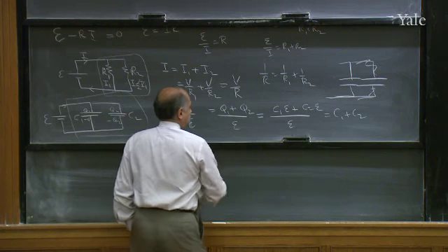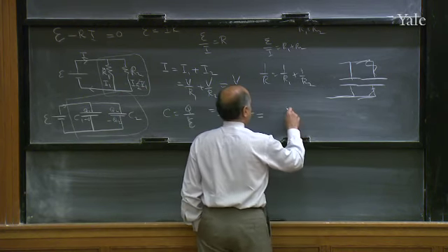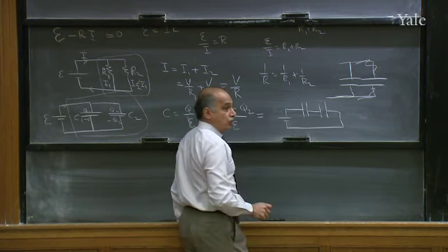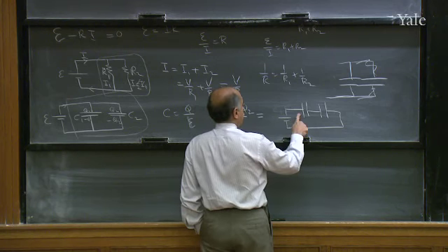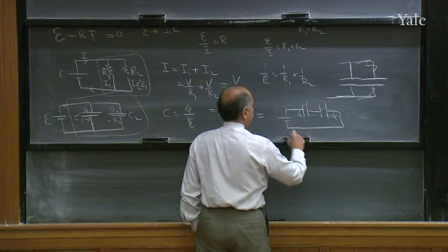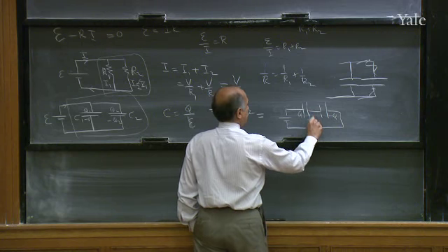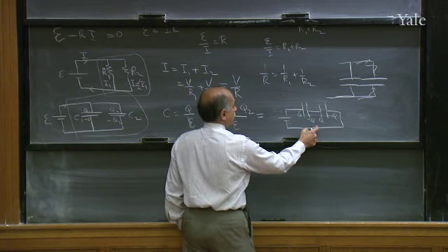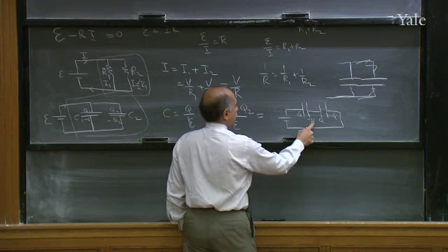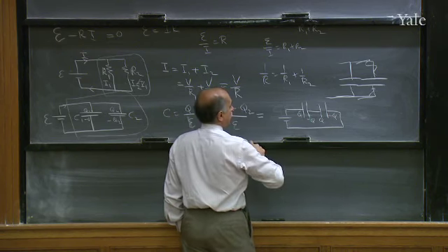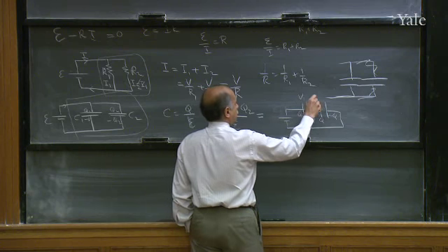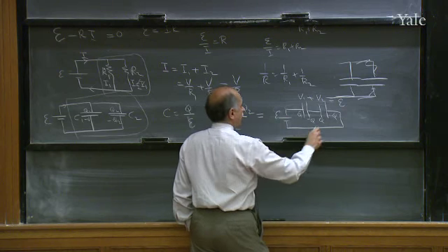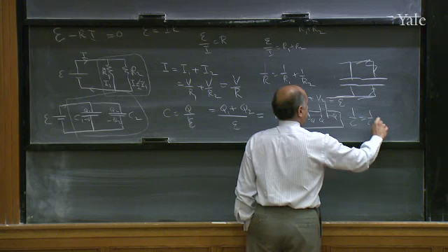And the final thing, which I don't want to do because I want to move on to more interesting things, is when you put two capacitors in series, what happens, you can take it as a homework problem. If you put a charge Q on this guy and a minus Q comes out to the other terminal, these two guys have no choice but to take minus Q and plus Q, because these two plates are isolated from the world. The charge they can have has to be equal and opposite, but minus Q has to balance this and plus Q has to balance that. Now if you use the fact that the voltage drop on this one plus the voltage drop on that one is the total EMF, you will find 1 over C is 1 over C1 plus 1 over C2.